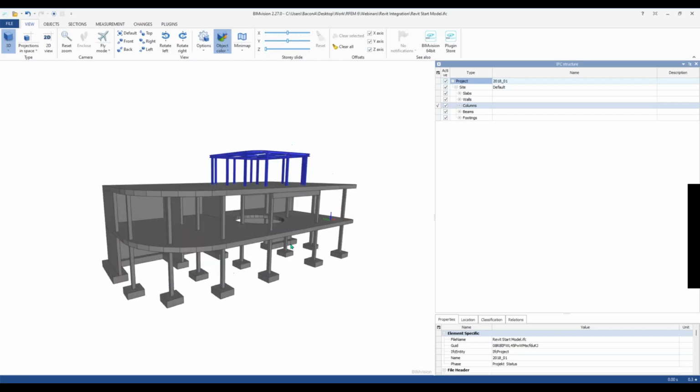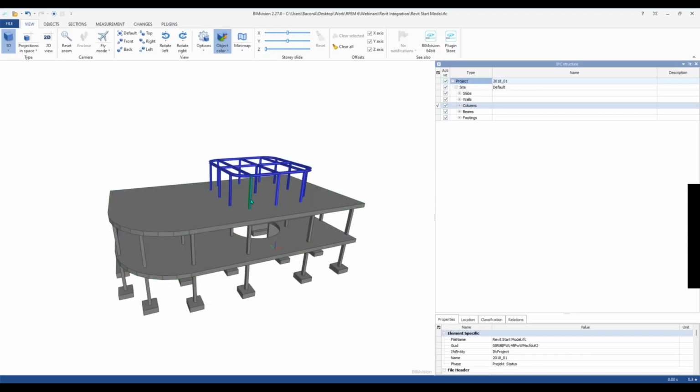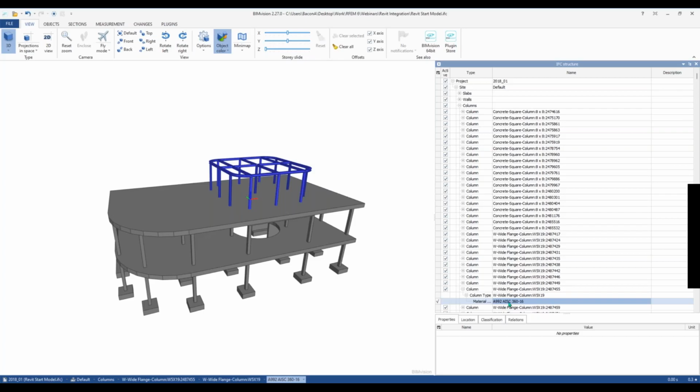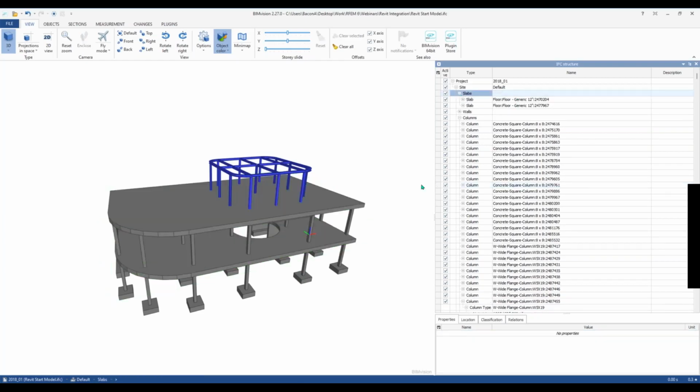We have our steel structure on the top, and the remaining concrete structure on the bottom. And what's nice with IFC formats is you can take a look here on the right-hand side, all of the information regarding cross-section and material that's necessary for an analytical model is all transferred over here. So for this W-shaped column here, we have a W5x19 along with the material here, A992 steel. And this is also done for the columns and then the slabs and everything.